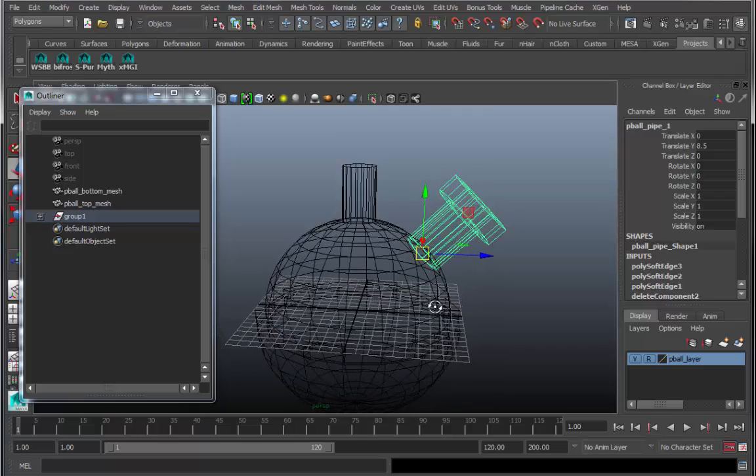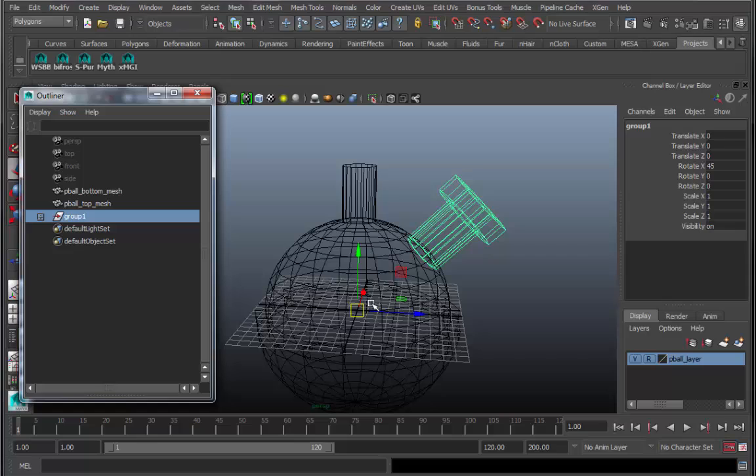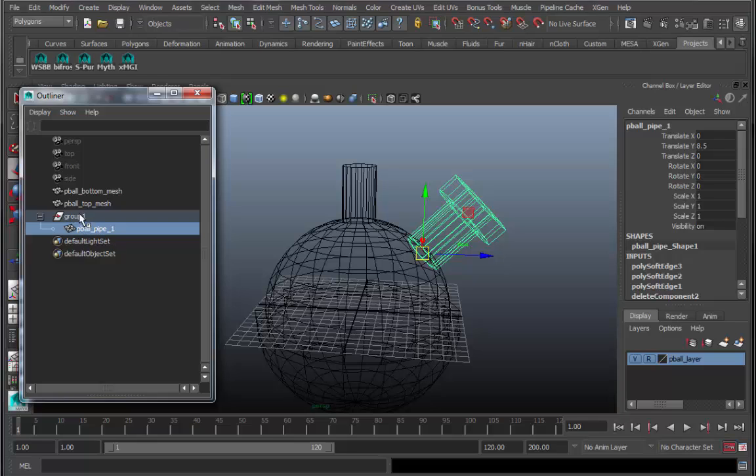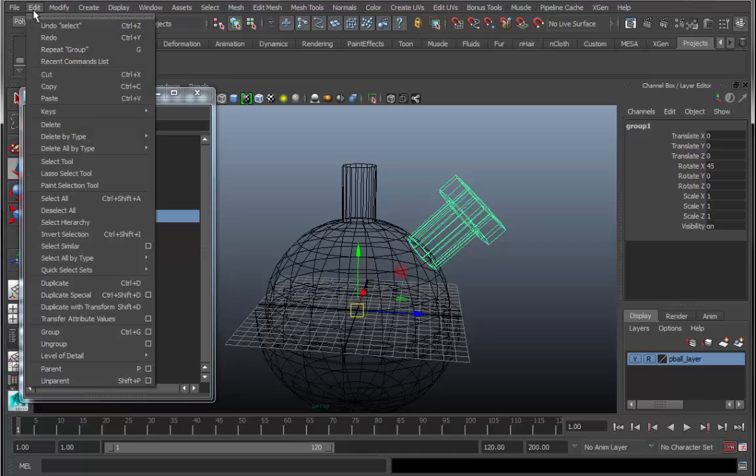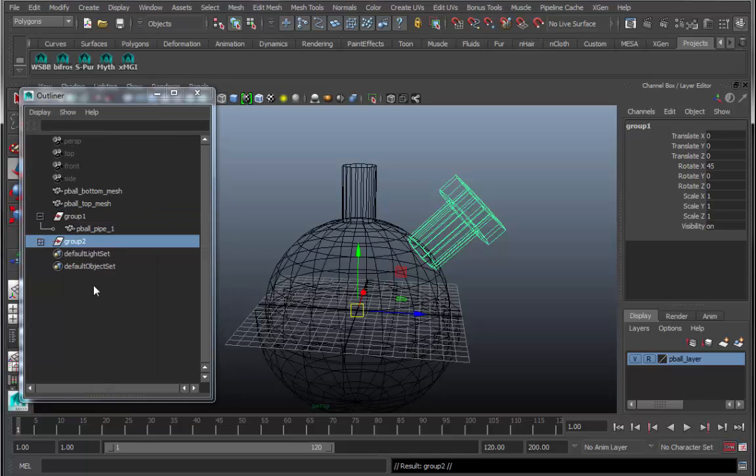It's pretty clean. So I want to create 2 more of these and have them on equidistant parts of the sphere, equidistant from this one. To do that, I'm going to duplicate this group. So again, here's an operation you need to be careful on. Make sure what you have selected is the group, not the mesh. With the group selected, come up here to duplicate. You have a new group? Wonderful. Rotate in Y. Let's do this 120.